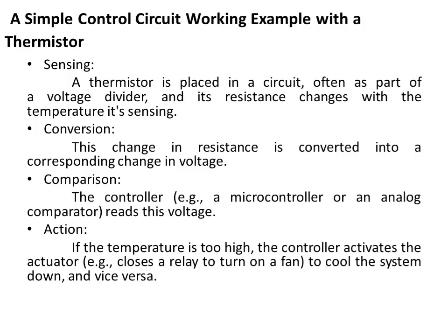A simple control circuit working example with a thermistor is given. Sensing. A thermistor is placed in a circuit, often as part of a voltage divider, and its resistance changes with the temperature it senses. Conversion. This change in resistance is converted into a corresponding change in voltage.